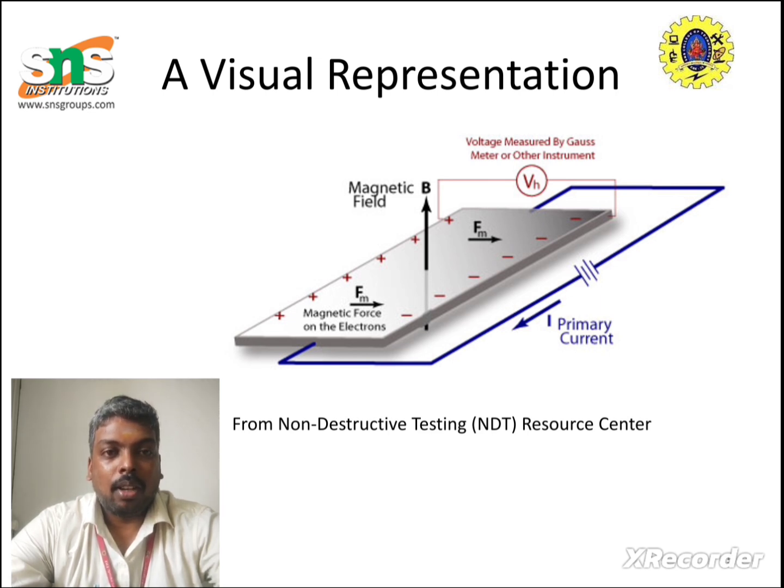If we name the faces, we can call face 1 positive and face 2 negative. The charged particles accumulate at one end, and opposite-sign charged particles accumulate at the opposite side, because the magnetic field deflects them by the Lorentz force. That creates the potential difference between the two junctions.